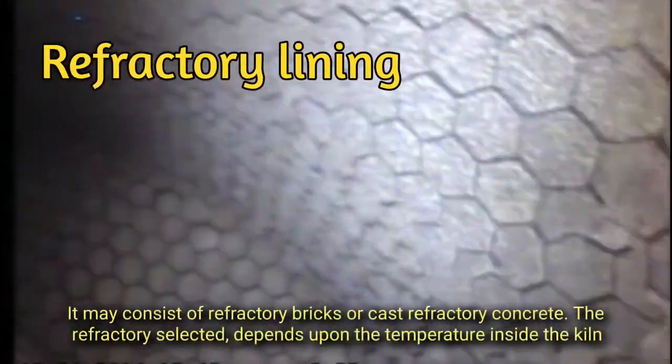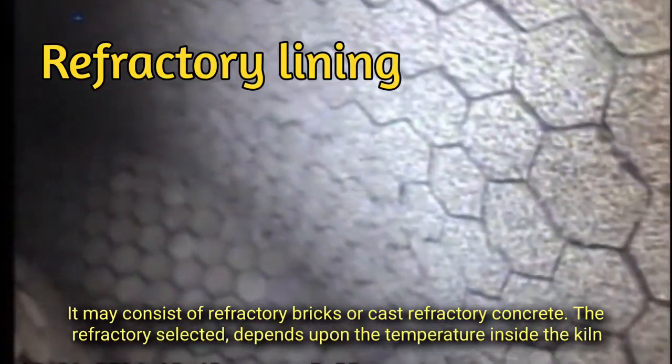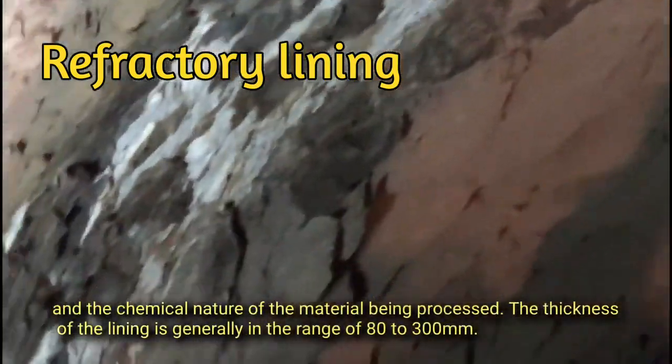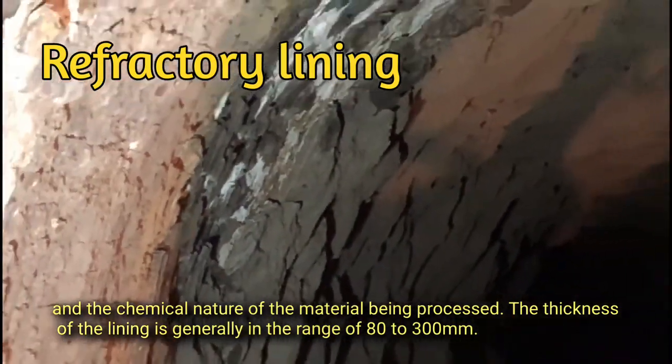Refractory lining. It may consist of refractory bricks or cast refractory concrete. The refractory selected depends upon the temperatures inside the kiln, and the chemical nature of the material being processed. The thickness of the lining is generally in the range of 80 to 300 millimeters.